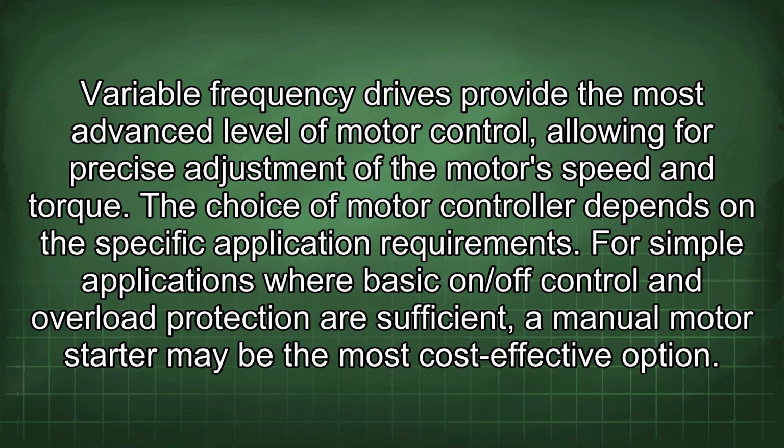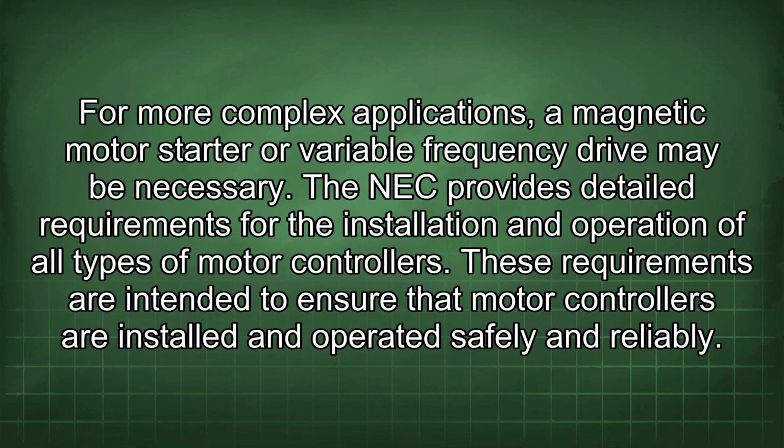The choice of motor controller depends on the specific application requirements. For simple applications where basic on/off control and overload protection are sufficient, a manual motor starter may be the most cost-effective option. For more complex applications, a magnetic motor starter or variable frequency drive may be necessary.